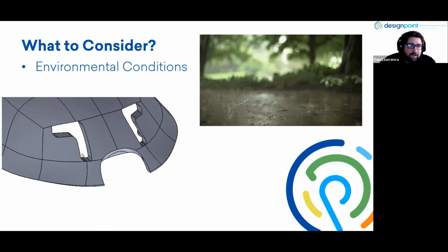But when we made these cutouts, they had a very, very sharp point right here, on that inner 90-degree angle. With that point, it's very prone to snagging leaves or branches. So we made sure that it was filleted and wasn't poking out at all, so it won't snag anything. Some other things that you might want to consider in manufacturing: is this going to be in a very harsh chemical exposure, immersed in any sort of fluid? These are things that you want to consider. They might drive some of the material you're using, or even, if it's applicable, whether to go through with the print.